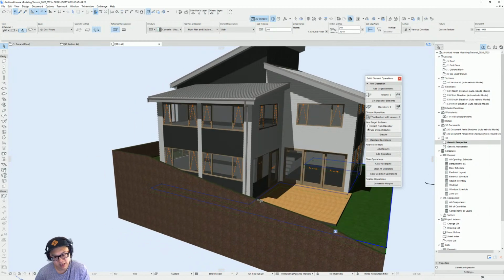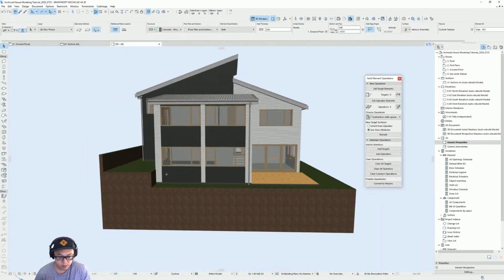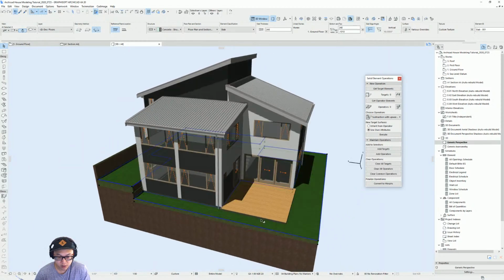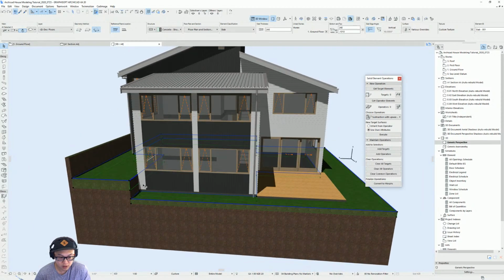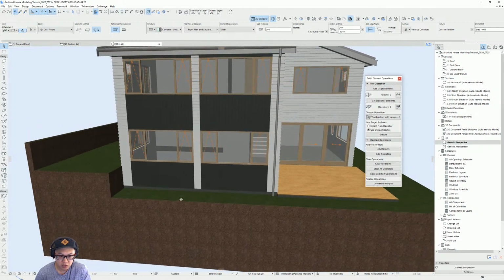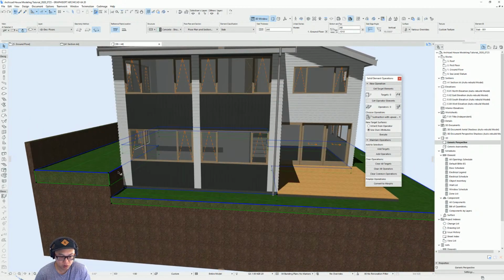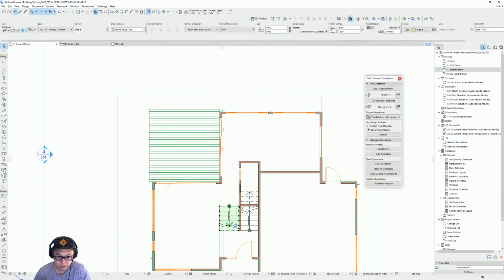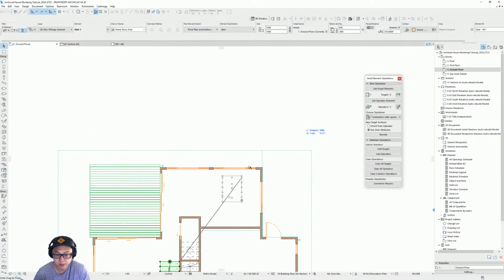I mean, it's not that nice. Anyway, let's see, so we get that. I think what I'd like to add now is a staircase on this side, and I know the drop is about 900, something similar, so I'm just gonna copy the staircase that's in here. I'm gonna Control C. Oh, I can just drag Control D, press Control to add, get that little plus sign, and click on one of the node,